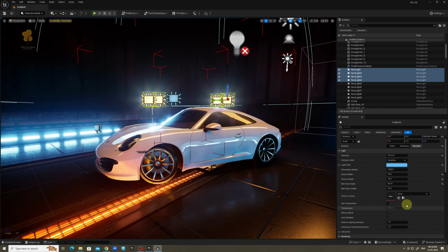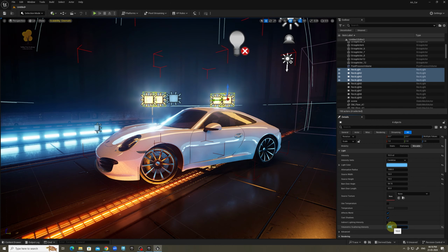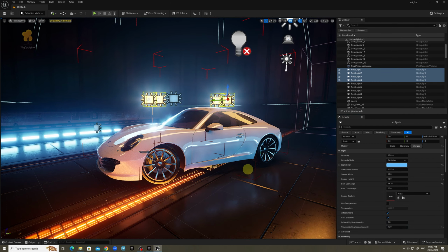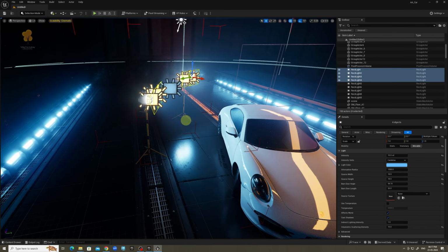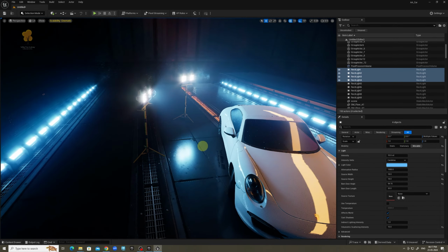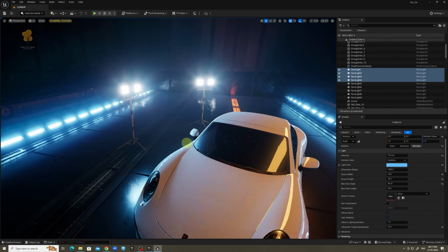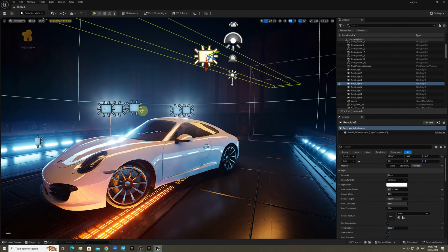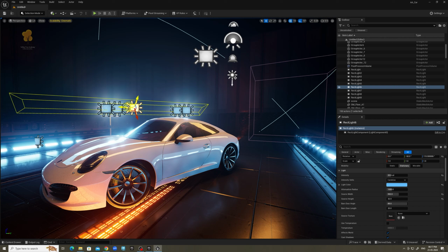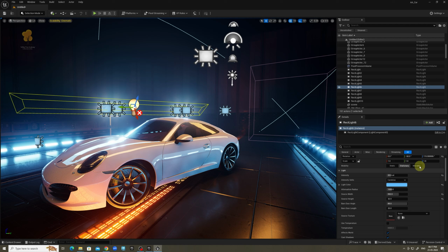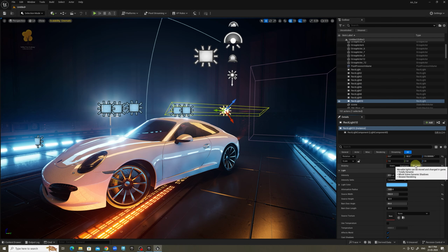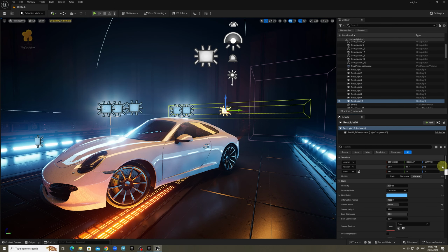Select this, all the 4 lights, and there is an option volumetric scattering intensity. I make it 10, and you see that so we're getting more light. Volumetric light is coming from this. I press G on the keyboard, you can see here. Okay, and please select this light, duplicate that light. And you see this is also, I have to make it movable, and set the rotation 0.